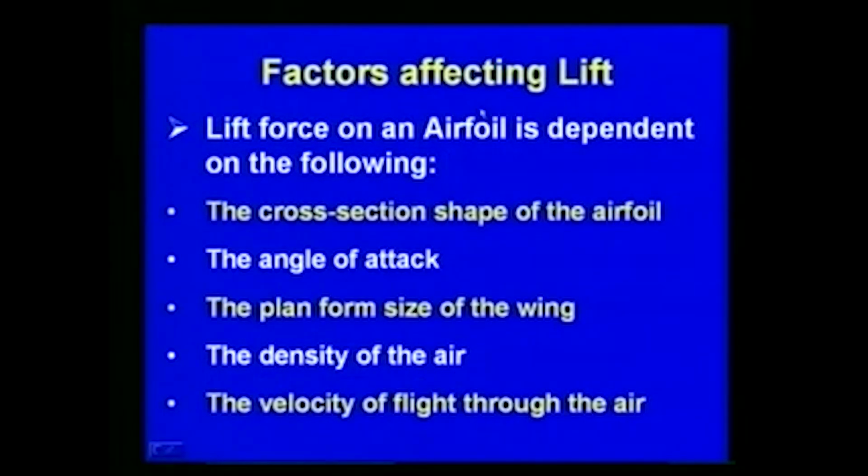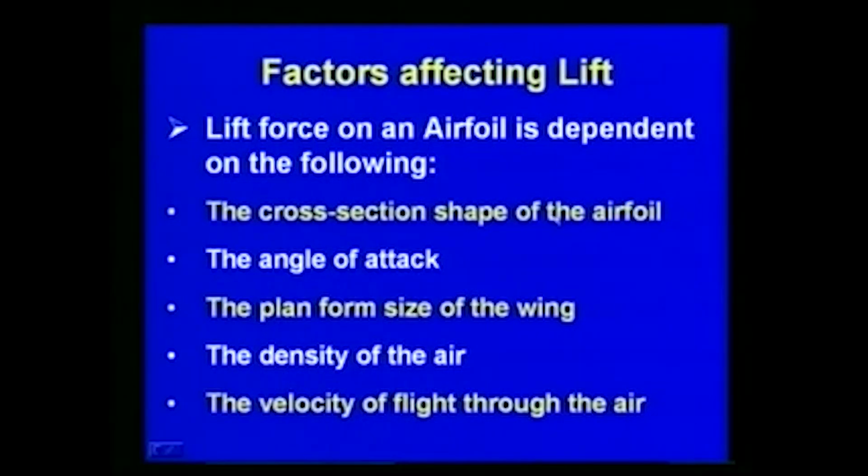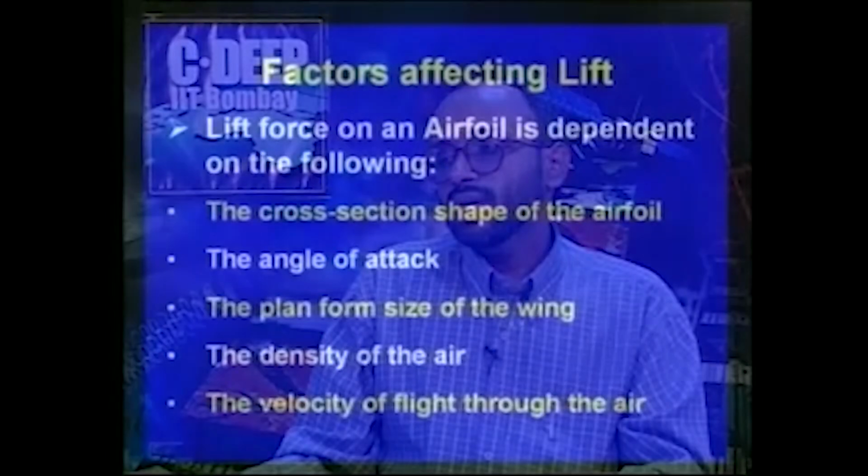With respect to the airfoil which we analyzed just now, the important factors affecting the lift are: the lift force on an airfoil is dependent upon the cross section shape of the airfoil, that is, how we designed the airfoil. Of course, the most important parameter is the angle of attack, and then the planform size of the wing.